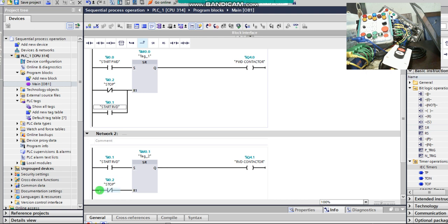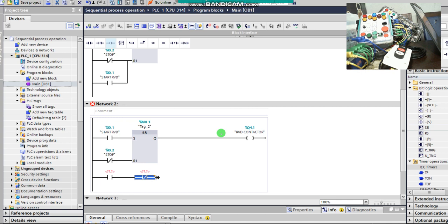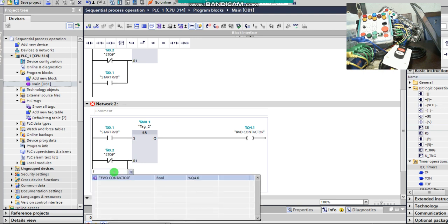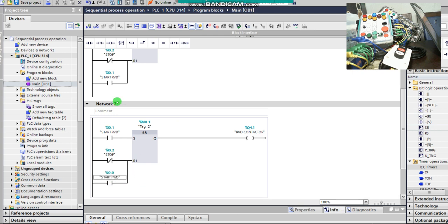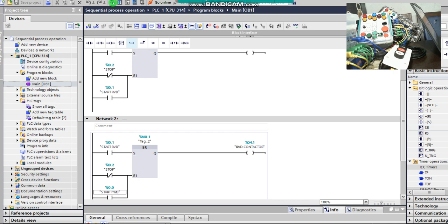The same thing is applicable here. You add the operation by adding this other logic. Okay, and I use forward here. Start forward here. Okay, so with this now, if forward operation is initiated and backward is also needed, once you initiate the backward operation, the command will be reversed immediately.